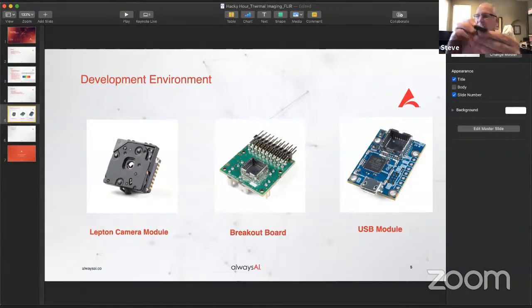As you can see, it's got these 2 rows now of pins. I hate that, because think about if you put those in a breadboard, right? The problem you're going to have as you go into a breadboard now, it's hard to get uniqueness out of that and so forth. It gets messy. So you have to almost go to a prototyping board that you can cut and solder in and so forth. Sorry, I got to hold it up here for everyone.